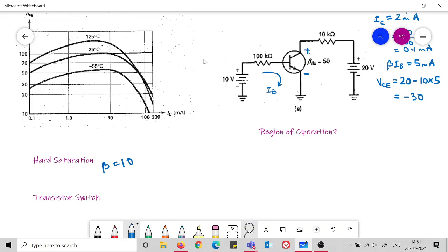So how the 2 different junctions give rise to the phenomenon, why the BE junction needs to be forward biased, the CB junction needs to be reverse biased, how we can set up this forward bias and reverse bias of the BE and CB junctions, how the VCC is contributing to the biasing, how the base side is quite independent of the collector side in the common emitter case, and the base side is giving rise to the current IC in the active region by multiplying it with beta times, solving the circuit.